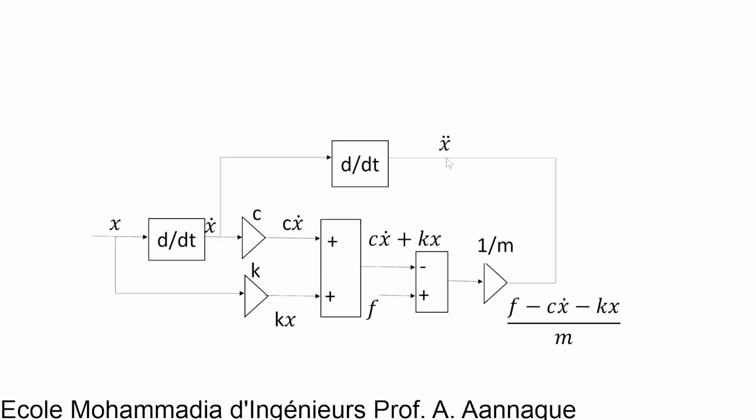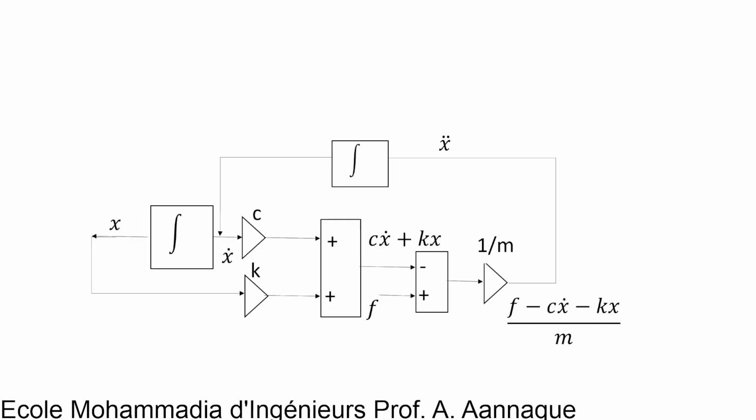And actually, working with integrators is better than with differentiators. Why? Because with integrators, we could use the initial conditions, which gives better control on the solution obtained. So instead of using a differentiator, we will use the integrator, and the model becomes this. It's exactly the same.